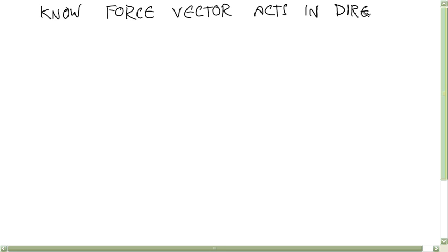Once I have that vector, I'm going to calculate the unit vector in that direction. And then I'm going to multiply that unit vector by the single unknown, the magnitude of the force, which is the cable tension. And that's going to give me a variable that only has a single unknown, say the tension T, and still represents a full vector, okay?